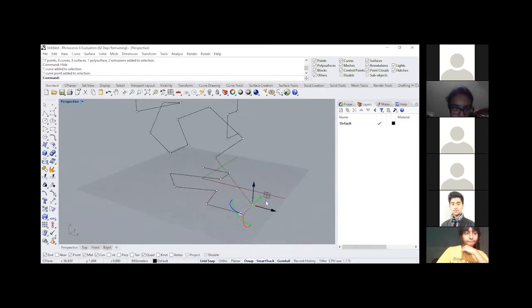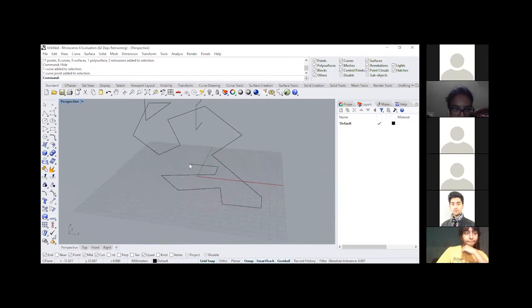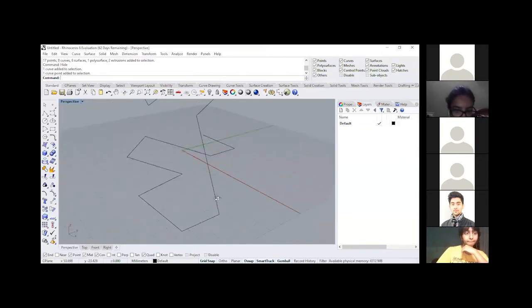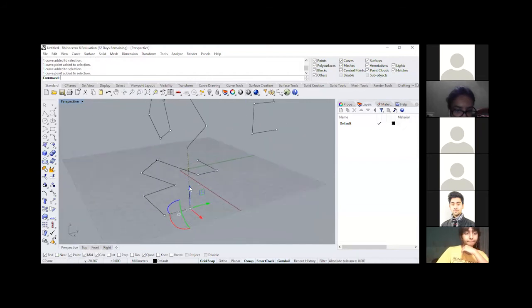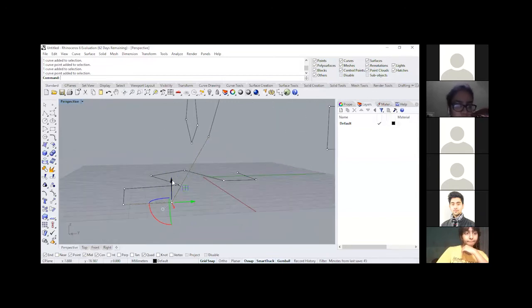So this polyline we started off with on the top viewport. We have this entire segment of this polyline, which we ended over here in the top viewport. Correct? And then we went on to the front viewport. Now you can see how, when we switched to the front viewport, it went to the base XZ plane.